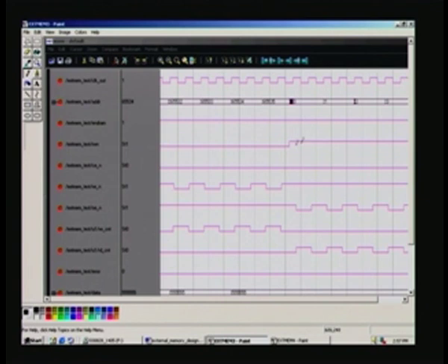So, now also notice that this OE bar is the read signal here, OE bar has become active here, and write has stopped. So, the safe state is the high state, that is the inactive state for the write; both are active low by design, and that is why it is like that. And you can clearly see that the write pulse stops here, with the switchover of RWN, and reads start here.